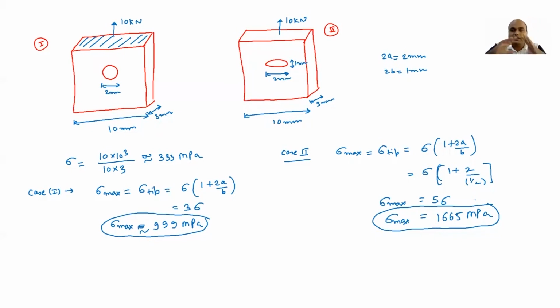So overall, in the stress-based approach, we have discussed the qualitative as well as the quantitative way, and the conclusion is that there will be a stress concentration at the crack tip. The maximum stress is going to be at the crack tip, and it is going to be higher than the applied stress. If that happens, at the crack tip you can go beyond the yield point, or it can also reach the theoretical cohesive stress.